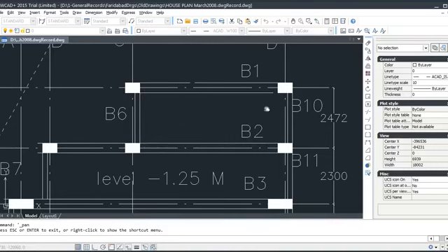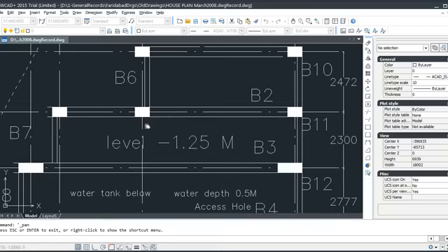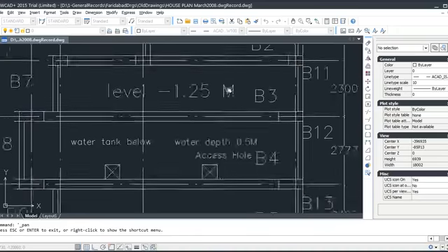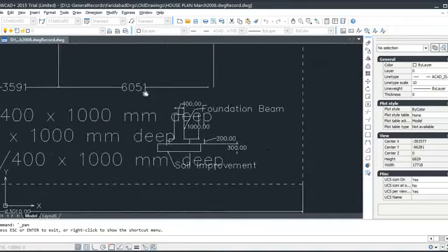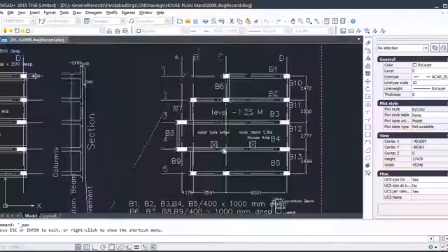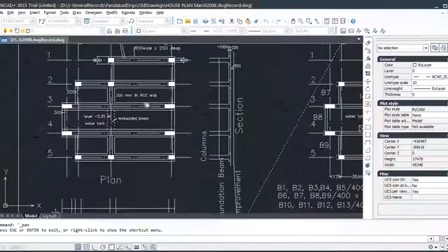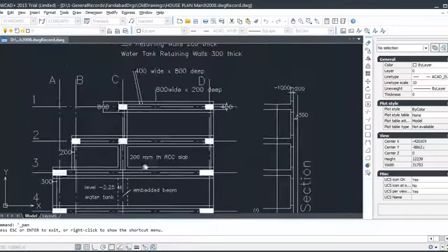So this trapezium portion shall go into this beam, this load shall go to this, and this load shall go to this, and similarly every portion is divided, and that load goes there accordingly. This is the basic principle, and if you don't follow it, your slab shall be out of load, unbalanced load.